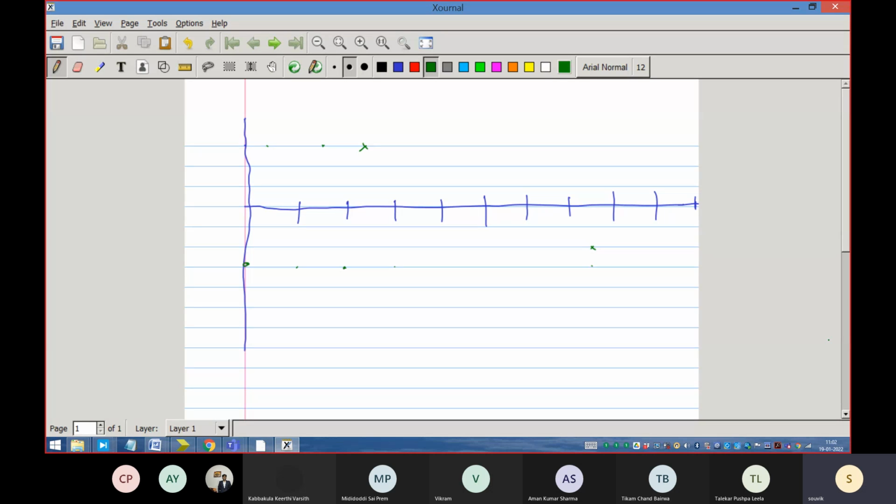So, this is some kind of a calculation, like somebody gives me a value of sine wave, some physical sine wave that must be applied at the motor terminals. Then I cannot produce that sine wave as a continuous function. So I produce the sine wave in an equivalent sense using a switching function. That switching function is essentially doing an average, the average over a period called the switching period, or TS.